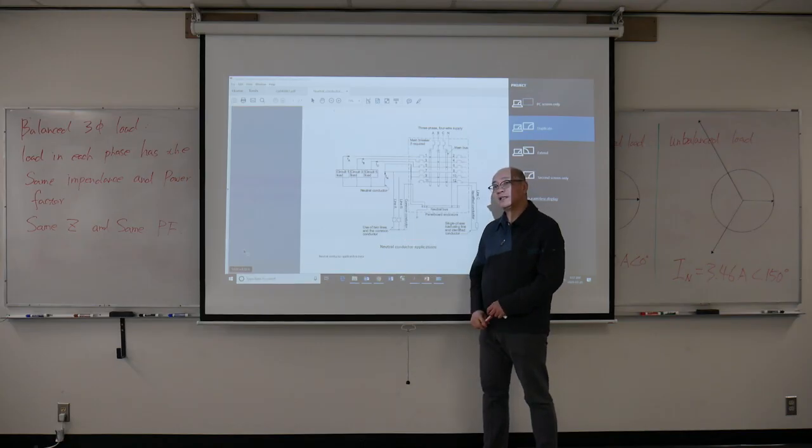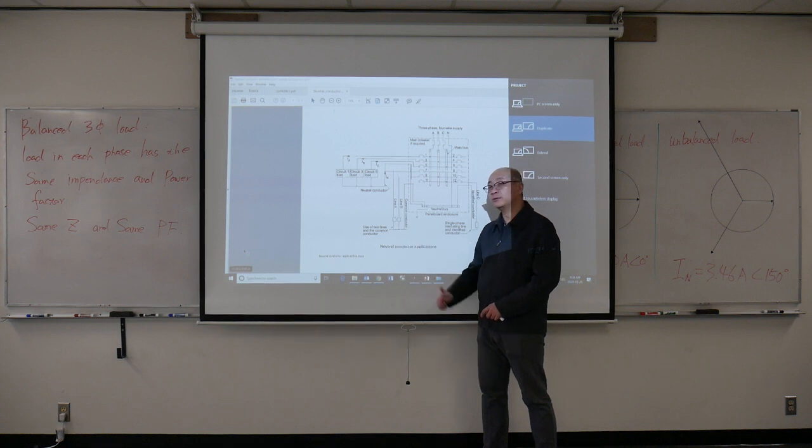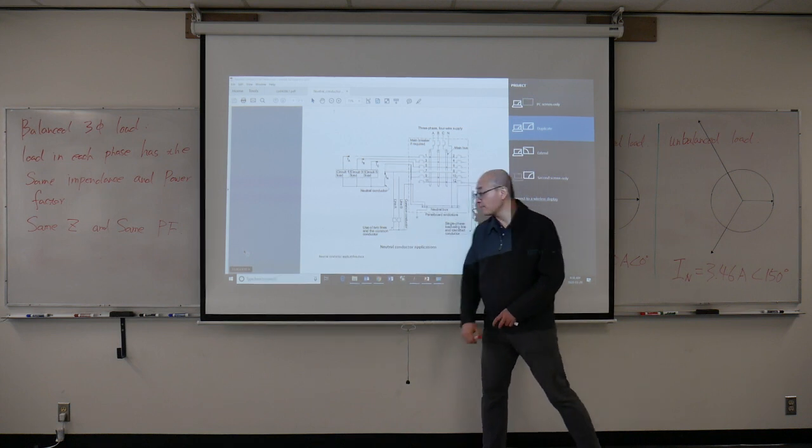That white conductor, we cannot call neutral anymore. That one becomes a common conductor. The definition for the neutral conductor is that it only carries unbalanced current. But this common conductor, even though it's white, is not carrying the unbalanced current. It actually carries the full current compared to the line conductor.